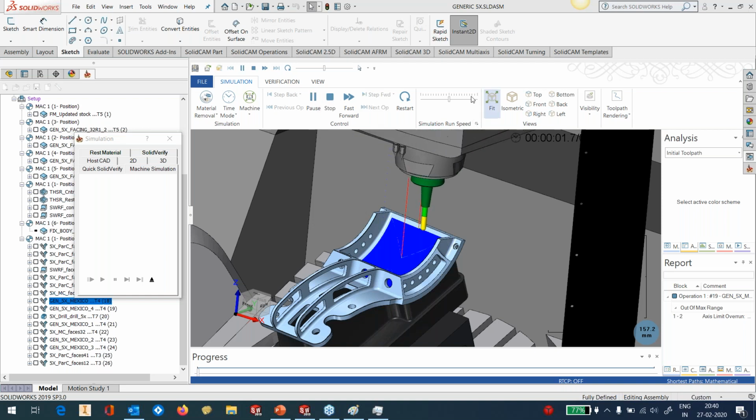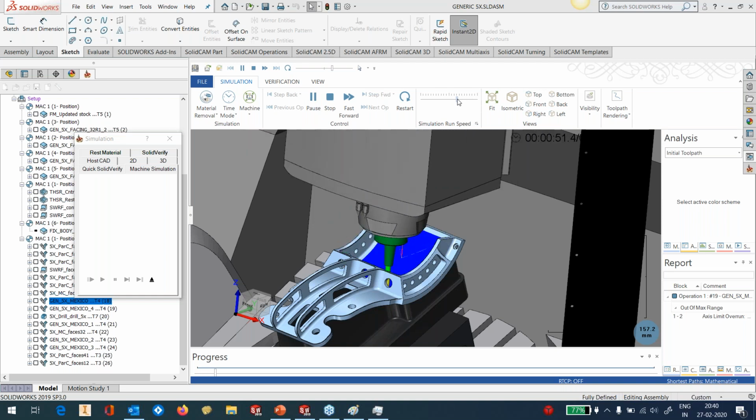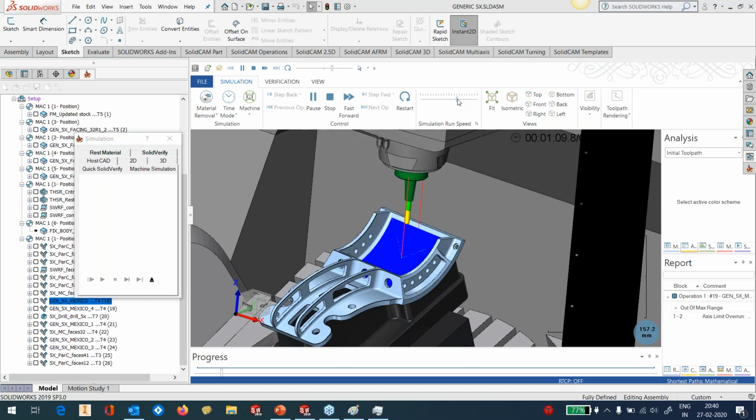We can see that it's completely 3-axis now. Complete collision-free 3-axis machining. You don't need to define or make any 5-axis toolpaths. It's a very powerful 3+2 functionality available inside the simultaneous 5-axis engine. You also know that when you do machining by locking your rotary axis and swivel axis, the surface quality improves dramatically, okay? Because you're not utilizing all the 5 axes, you're only utilizing the X, Y, Z axes, and locking the other 2 axes.